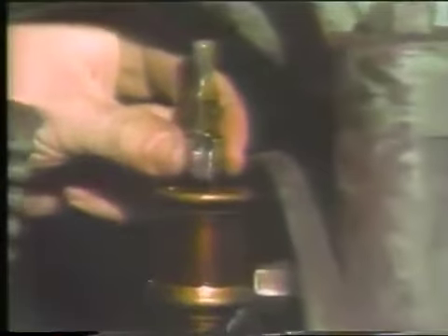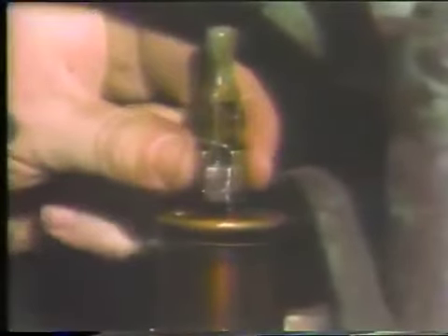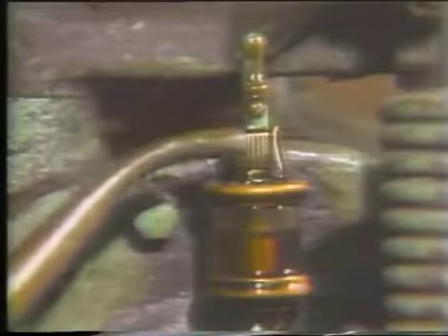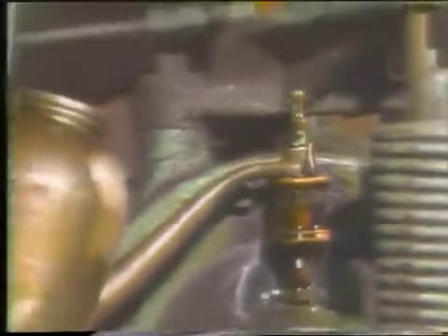A knob on the top of the reservoir is used to adjust the rate of the drip. The proper rate can be determined by either referring to the operator's manual or by asking your supervisor. There's also a lever that is used to stop the flow of oil when maintenance is required or when the machine is shut down. Generally, new oil is added by pouring it into the top of the reservoir until the reservoir is full. Any or all of these systems may be used in your plant.